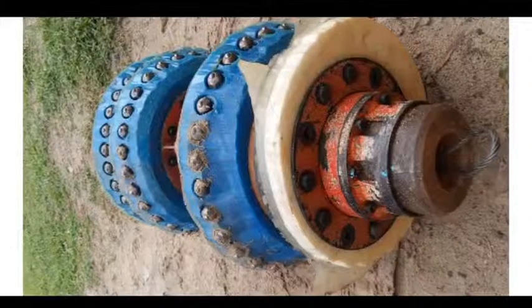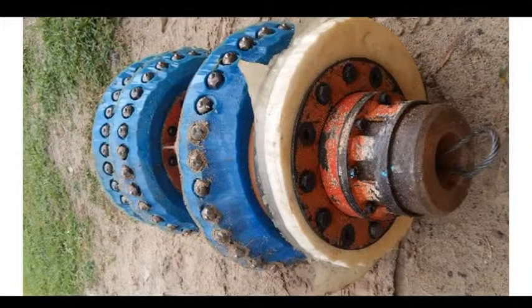Next. Like I said before, pinwheel pigs, we don't use them now. Some of you who are entering the industry now may not have seen it before. It's because this is not intelligent enough. With the vast amount of scale that we had in some of the pipelines in Nigeria, it used to go in and attempt to remove all the scale at the same time. So as you move, there's nowhere to move except for the pig to get stuck.